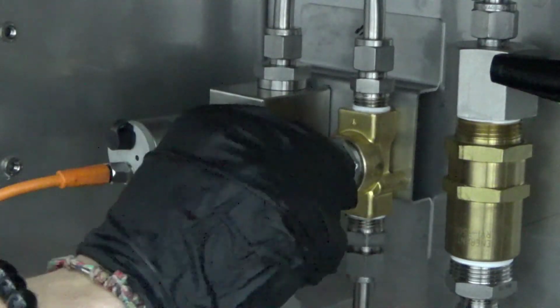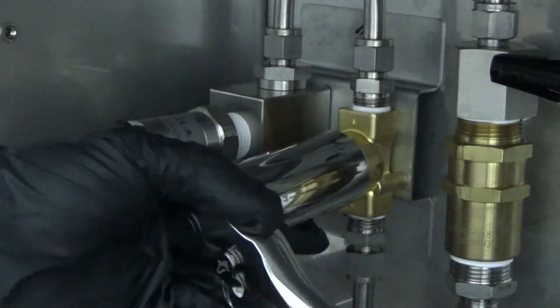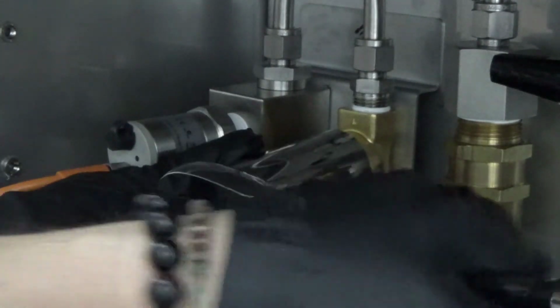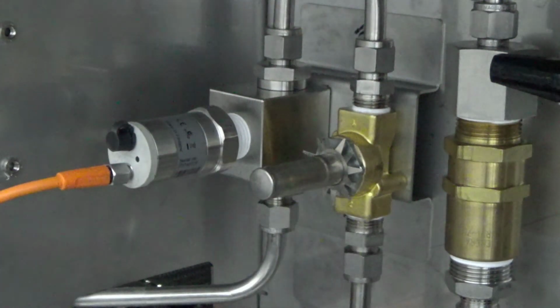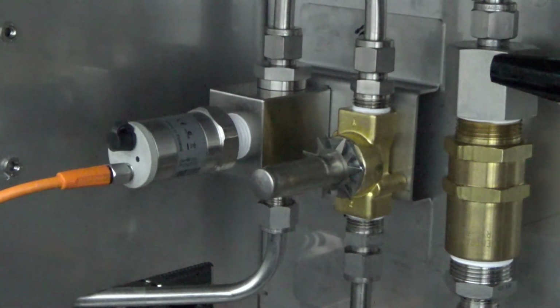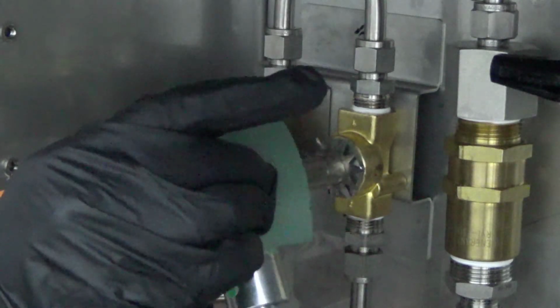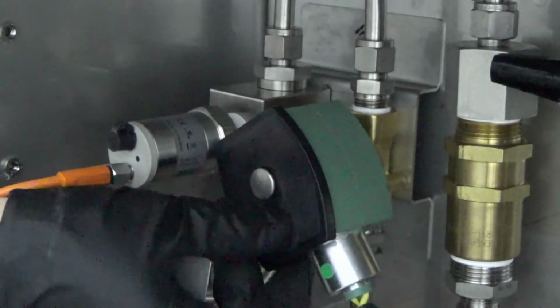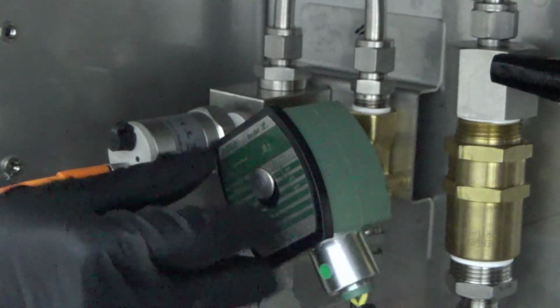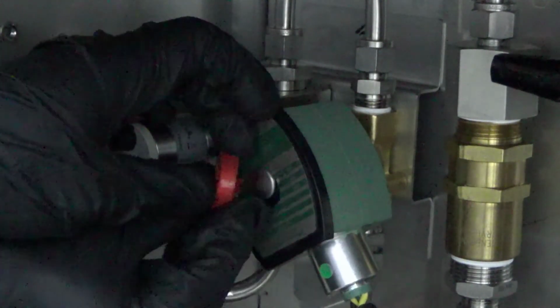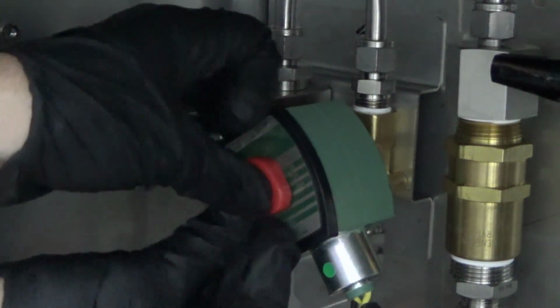We can now reassemble the exhaust solenoid. Again, pay close attention to the orientation of internal components when reassembling. Once the solenoid has been properly tightened, we can reassemble the coil body. First slide the washer on, then the green coil body. Now, use the mating feature to reassemble and mount the faceplate of our solenoid. We will finish this assembly by reapplying the red cap.